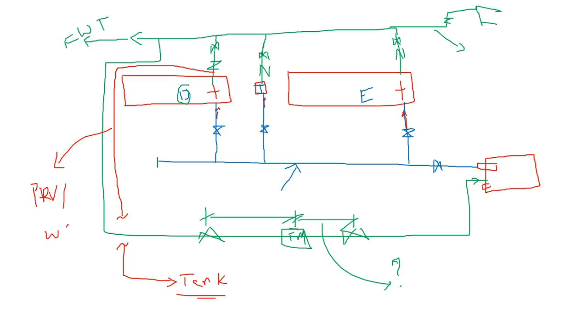Now coming back to the exhaust line. From the diesel engine exhaust we will take one pipe, and we'll take this pipe outside the building, and this pipe sizing will be calculated based on derating factor calculations from the engine manufacturer calculator or calculation sheet.